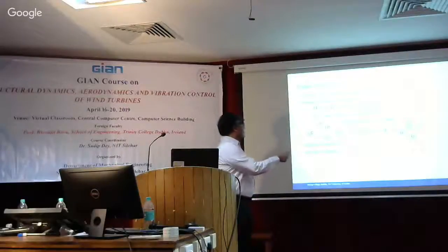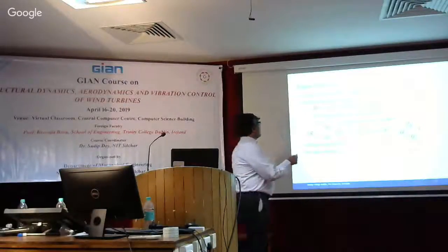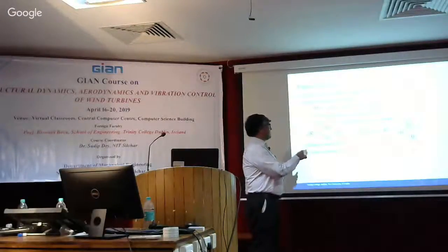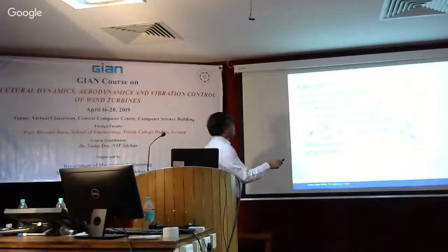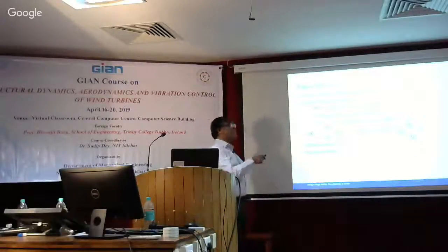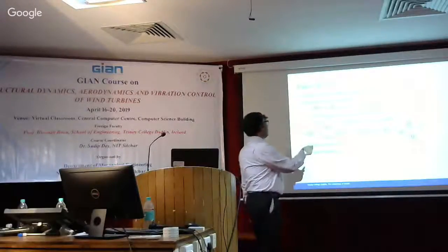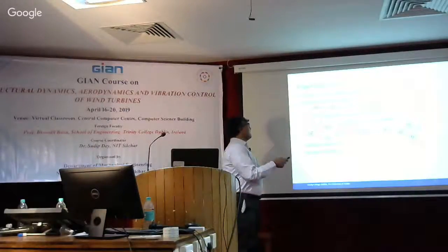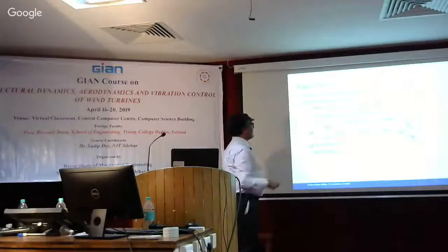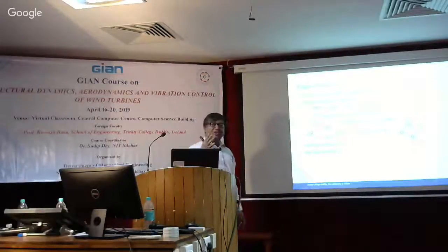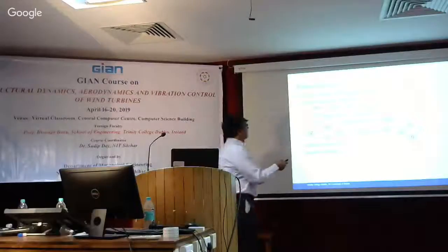Now, if this is the case, then if we can change the force in such a way that it is going to be like alpha minus x dot, then what happens is that this term, when taken on the left hand side, will actually be plus x dot, and will add some damping to it. So essentially, you can generalize it. This can be alpha 1 plus alpha 2 x dot, and alpha 2 has to be a negative quantity there. And then when we take that on the left hand side, it will add to this x dot term. So you'll now have damping of d plus alpha. So by changing the load, essentially in some fashion, we can introduce additional damping to the system.